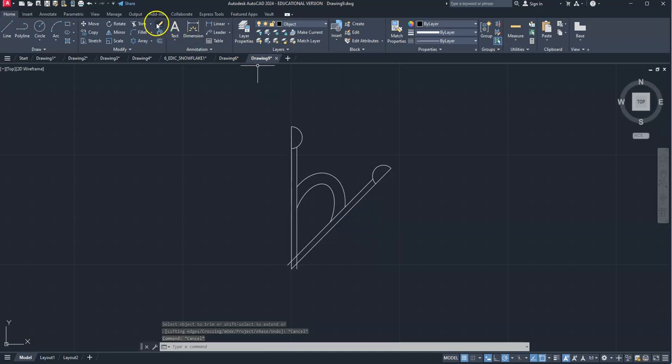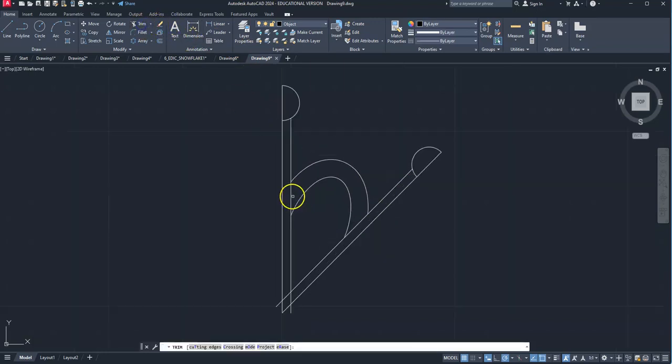Oh, and I can actually trim these connectors as well. There we go. Now I'm going to use X-line, XL again, my X-line. But instead of choosing horizontal, vertical, or an angle, I'm going to actually select these 2 points. I want this indefinite line through these 2 points.